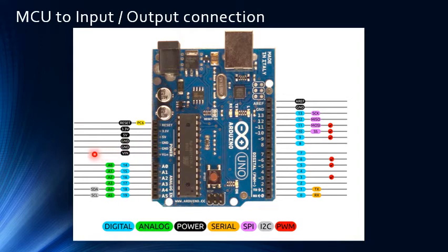you apply the voltage input to this pin and to the ground. You can apply to this ground or that ground or that ground, all the same, because all of these pins are connected. So you apply, let's say, 9 volt here with this ground, and because there is a regulator here, the regulator then outputs 5 volts that's needed by this board. 5 volt and 3.3 volt is the output. You should not connect the 5 volt directly to here.